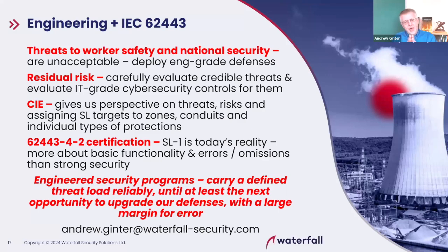The gateway makes copies of servers. It's usually a client on both the IT and the OT network. It's a client of the OT PI server or the OT OPC server or some other server on the OT side, logs in once a second, asks for everything that's new, gets that snapshot, sends it out through the weird one-way hardware, and on the outside populates an identical server. If it's PI on the inside, it's PI on the outside. If it's OPC on the inside, it's OPC on the outside.